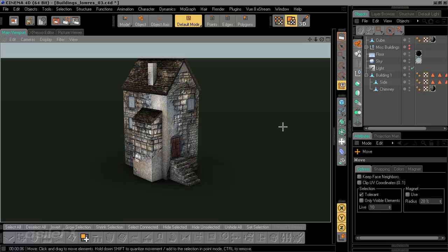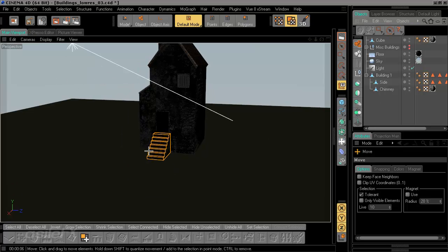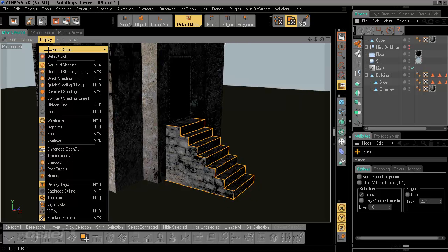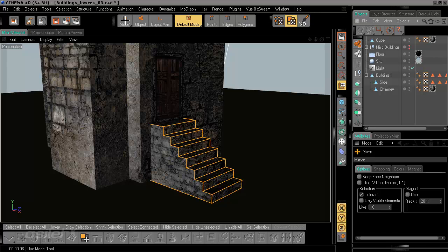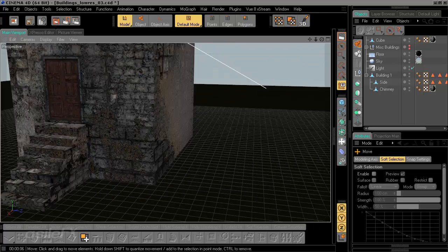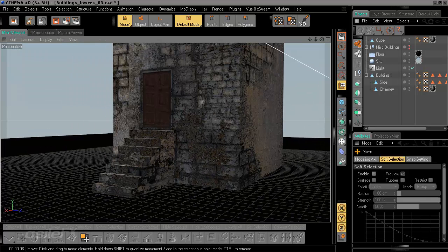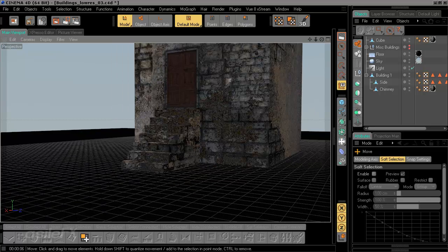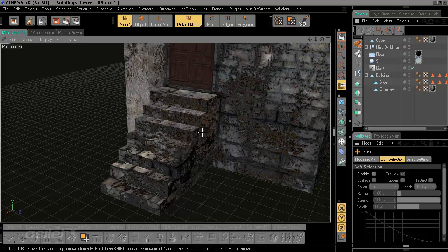And now you can see the stairs showing up in the render. If you want to bevel the edge to pick up a highlight, you could just select all of the edges and bevel them. You will need to restructure the UV map if you do decide to do that. And it looks like my display is once again a little bit off. But for the most part, if we were going to bevel this, we wouldn't need to bevel all the edges, just whatever we would want to pick up a highlight.